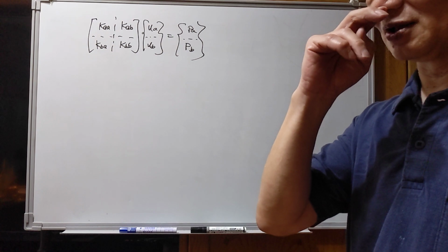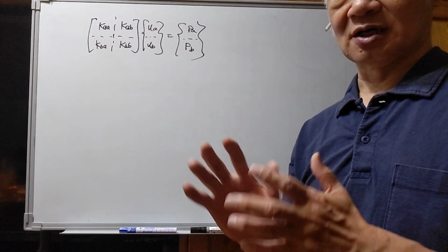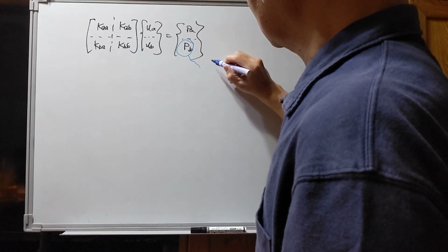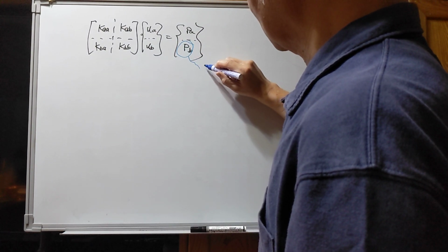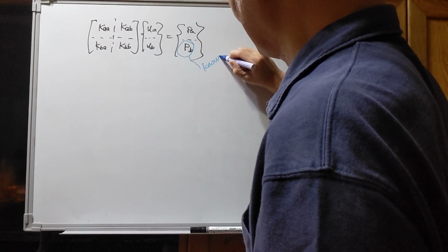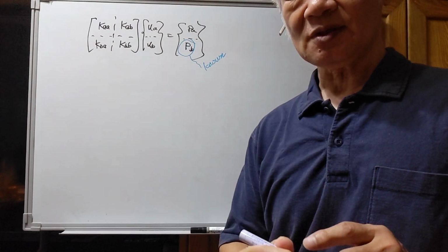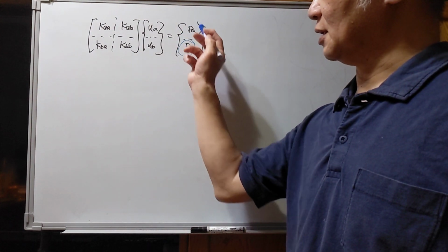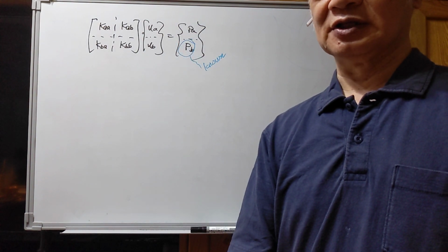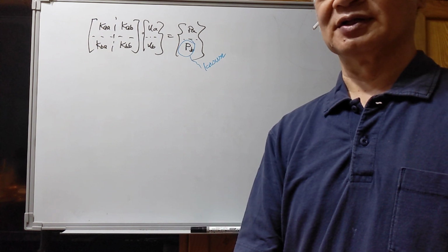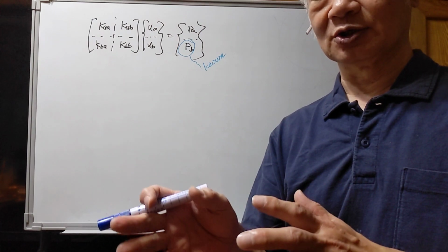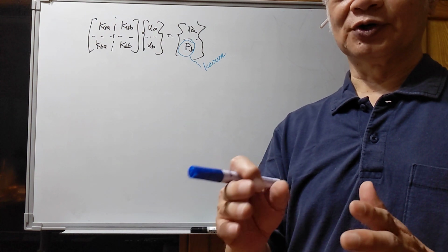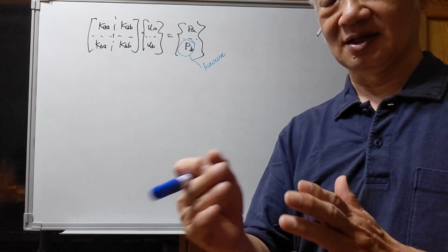Okay, and if you would like to do the static condensation, you must have some static conditions. And in these derivations, he assumes the PB are the known values. Okay. Remember, when you use the element stiffness matrix, usually at this time the elements in the force vector, you don't know the values right now. We know the applied loadings, so we know the external load applied to this joint, but we don't know how much shear will be in any elements.